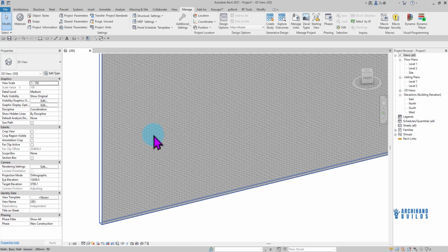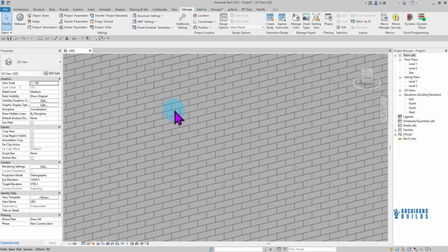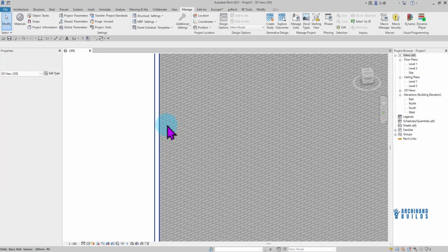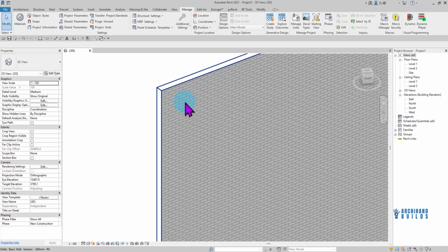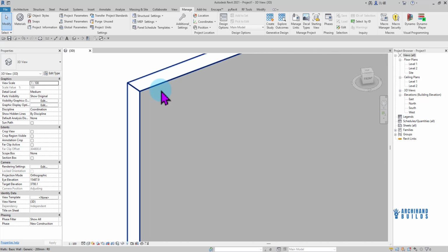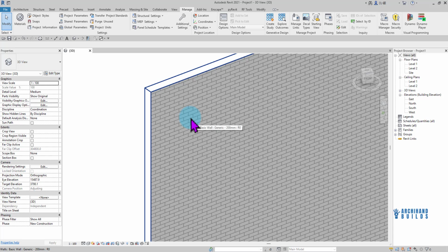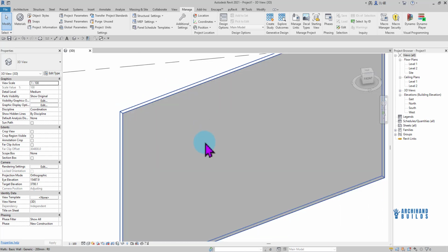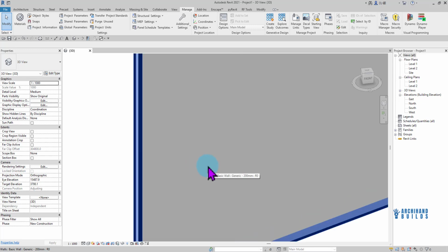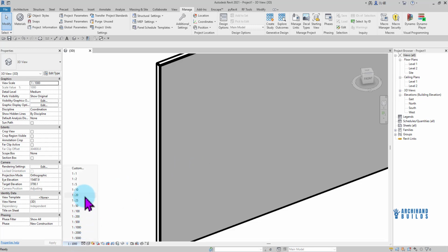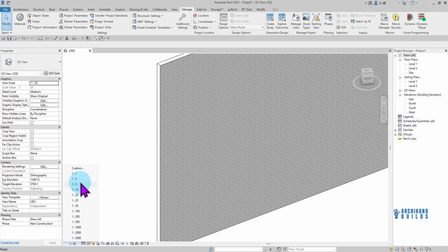So now you can see with our surface pattern, we have our pattern of a brick shape going inside there, and on the background we have an ash color. We can decide to take off the ash color over there. Now one thing you're going to realize is that when you change the scale to any scale you want, it doesn't affect the pattern. So when I change to 1000, let me just bring it down all the way to 20, you notice it doesn't affect the pattern.